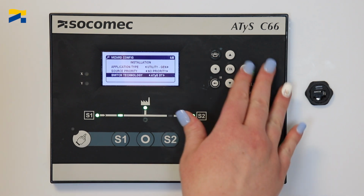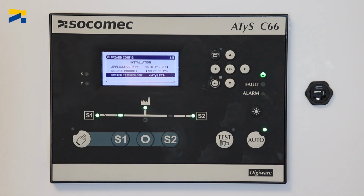Next is the ATyS FT, which is an open transition, to be selected when using an open transition single operator power contactor switch with two positions 1 and 2. In this configuration, the in-phase transfer and monitoring will be automatically enabled. Next is the ATyS UL. This is to be selected when using a motorized transfer switch, such as the Socomec ATyS UL.